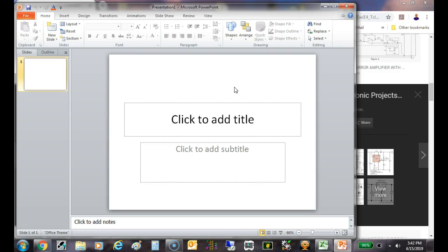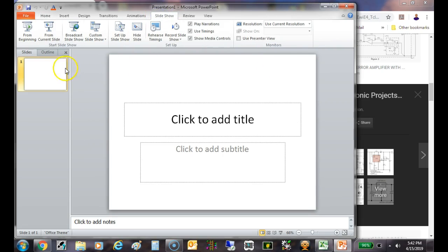And voltage is a relative term. The conductor has nothing to do with the amount of voltage. That's what the insulator's in there for, to keep that voltage from pushing that current where it's not supposed to go, right? So the insulator is rated at a voltage. The conductor is rated at a current. The problem is there's no such thing as a conductor that has zero resistance. So the main purpose of the conductor is to get the power from the power supply to the load. And it does that through current, right?